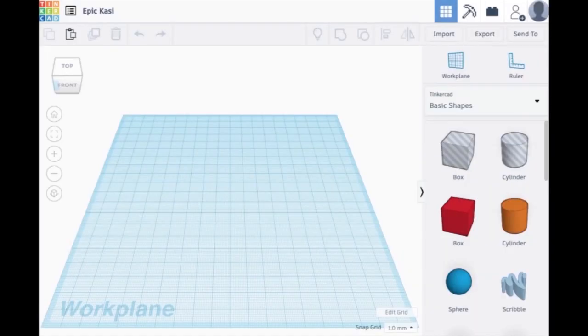When you first open up Tinkercad in order to make a new design, you'll see a screen that looks like this. It consists of various areas, a selection area for various models you can begin with, and here we see what is known as the Workplane, and it's here we'll begin this explanation. The Workplane consists of this area on which you construct and design your models.